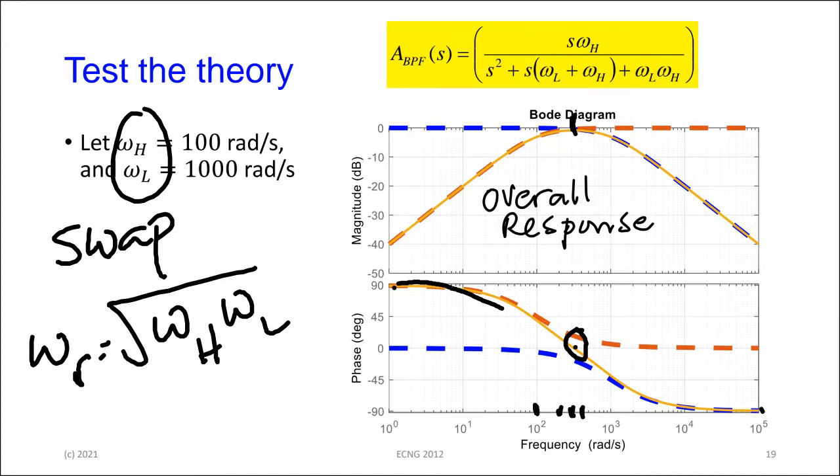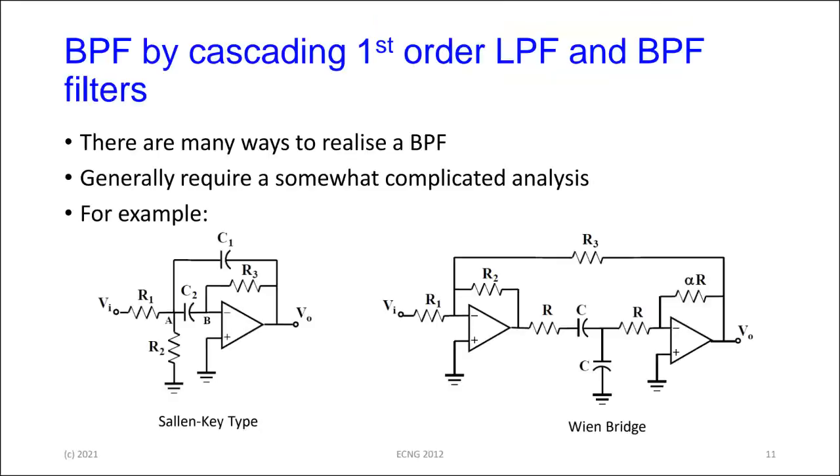Okay, so that's the one way. So we make the bandpass filter a very simple, straightforward design by cascading a low pass and a high pass first order active filter. We could do that. And in this case, it's actually simpler than some of the previous designs that we looked at. For instance, the Wien bridge requires two op amps, so we haven't gotten more expensive than that.